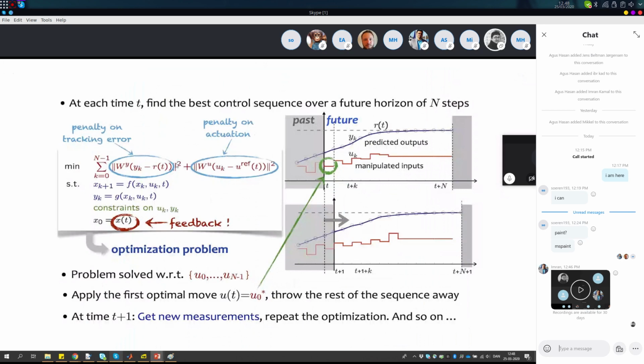So you want to minimize the difference between your current state and your desired temperatures subject to some constraint, and the constraint is basically the model of the temperatures in the room. Okay. So in the sense that quadratic programming problem has a lot of application, therefore it has a special chapter. So from linear, we don't go directly to nonlinear, but we first consider the quadratic problem.